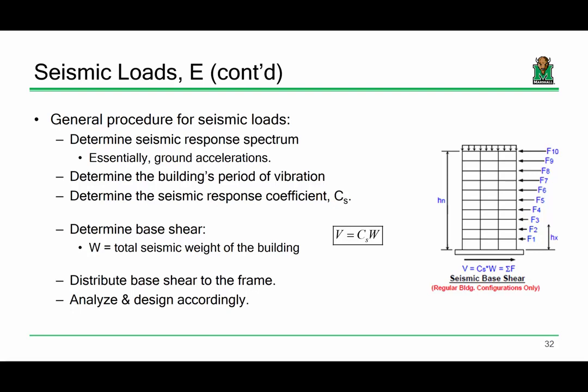And so we call that the base shear because here's the building and the earthquake is moving like this, so it's sort of like it's shearing the building. And then the only thing you have left to determine is, how much of that shear would get applied to each story? How much goes to the first story? How much goes to the second story, et cetera? And then you can break out RISA or whatever software package you want, or if it's determinate, do it by hand and do your structural analysis. That's pretty much it.